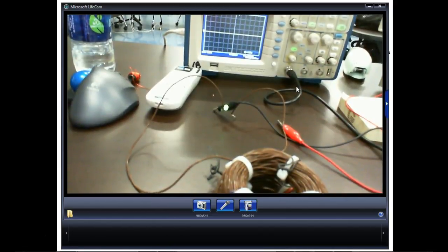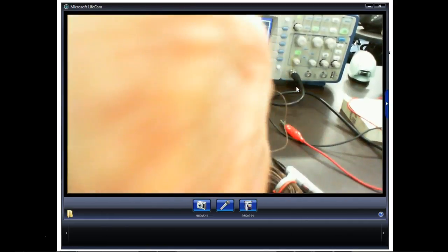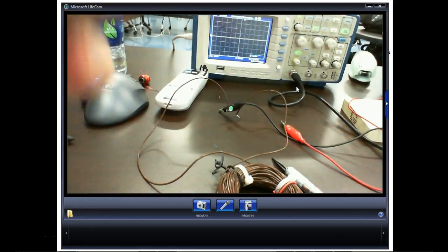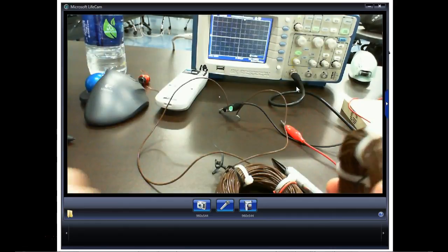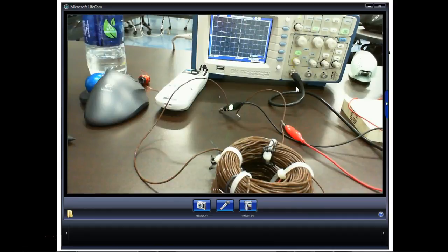What did I just make? So there's no electrical connection, guys. So here's my function generator. This is what we call induction, where I can induce a voltage into another coil of wire by just using AC. This only works with AC. DC has no what? It has no motion. But there I'm using an electromagnet, but I'm constantly changing the magnet. I'm changing the polarity. So it goes positive, maximum current, swaps to zero, swaps around, and the magnetic field goes out and keeps swapping back and forth.